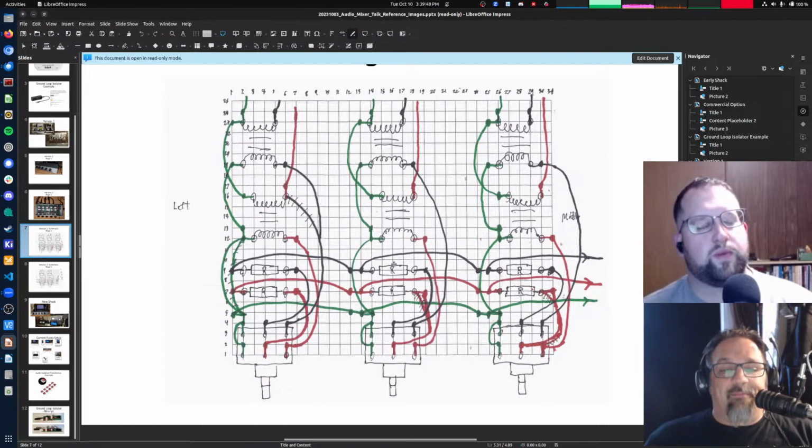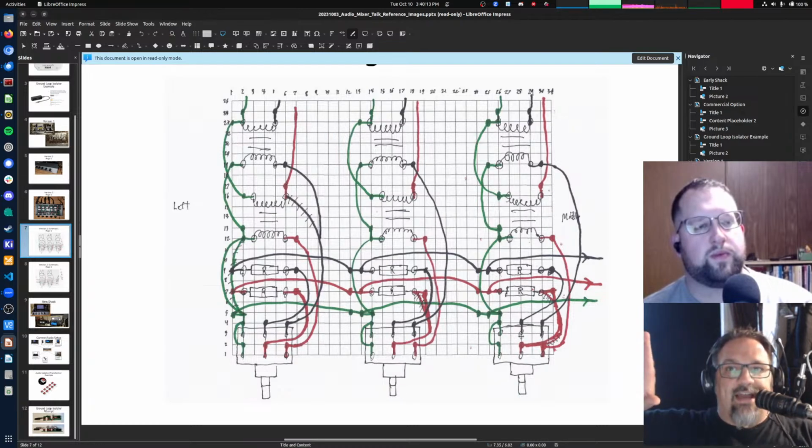Okay, so think about that for a second. If you didn't have these resistors here, and you just tied the wipers of these potentiometers together and connected them to an output, like if you only had one of these channels and you didn't have all of the other ones, you wouldn't need this series resistor. You could just go straight from the wiper directly to the output connectors. And that would be safe to do. But because you have multiples of these coming together, you need to have these series resistors.